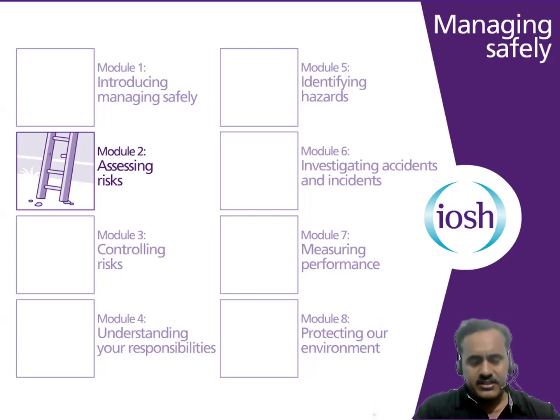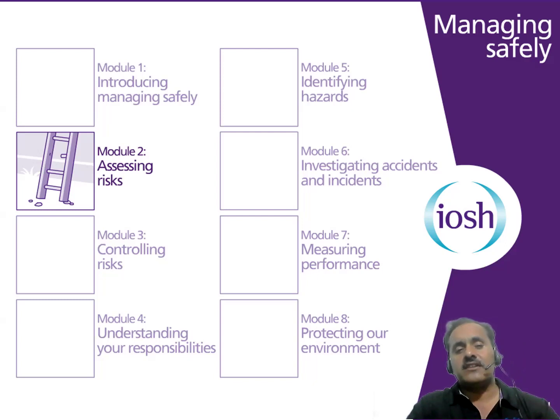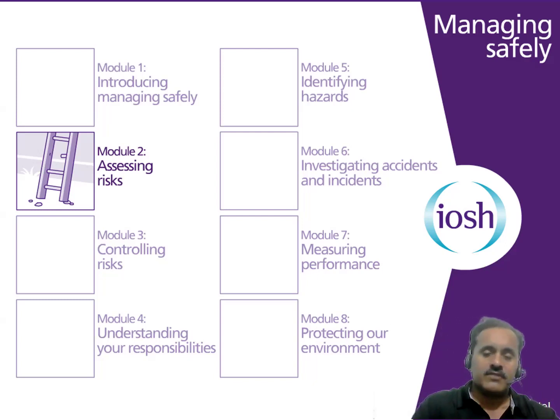If there is an excavation, a confined space, working at height, scaffolding work, or manual handling, then before doing these tasks, the risk assessment will be conducted by the safety officer. In risk assessment, we try to identify the hazards, what the possible hazards can be while doing crane operation, confined space work, or working on scaffolding. So who will identify the hazards, and at the same time who will suggest the control measures, so that we can ensure that this crane operation or scaffolding operation can be a safe operation.